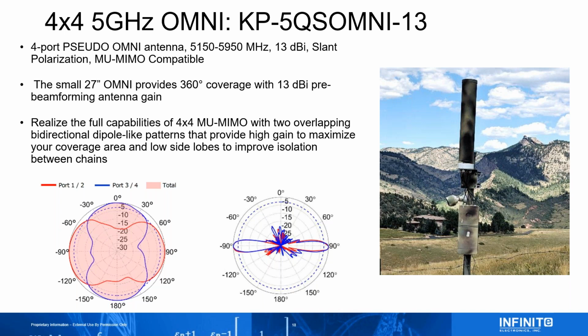Or you have a lot of clients and you want to charge them, and they have low data rates, and it's just all about investing. When you're starting out, you put an Omni first. Or if you want to get 360-degree coverage, and then once you build up the capacity and your clients, then you can justify buying another radio. Until that point comes, you start with that Omni, go to 120-degree sectors, then 90-degree sectors, 65 degrees, and if things get crazy, you go to 33 or 45-degree sectors.